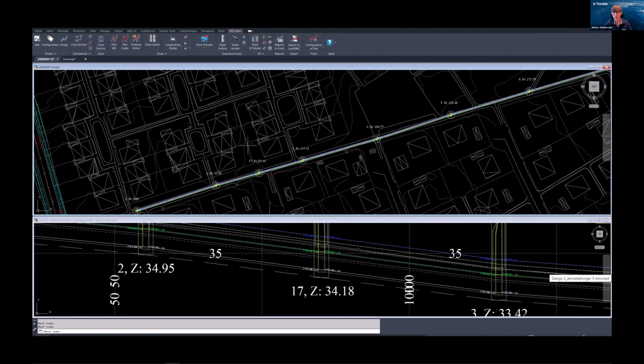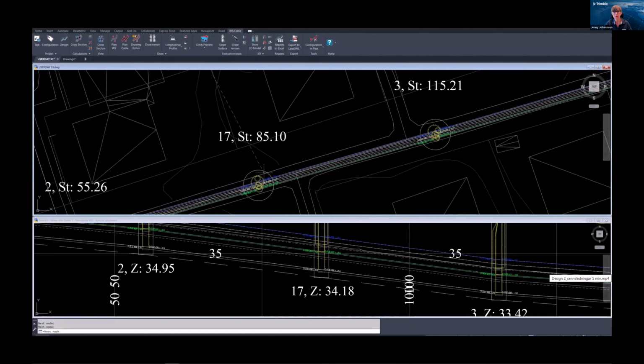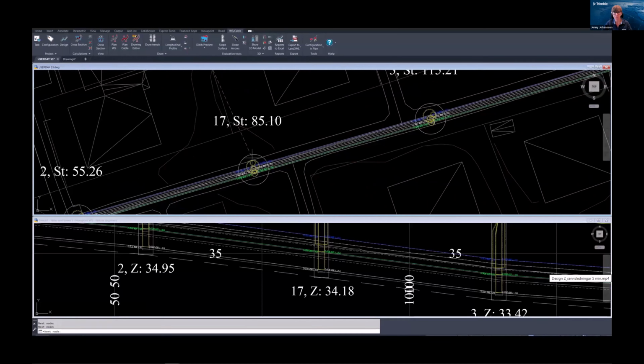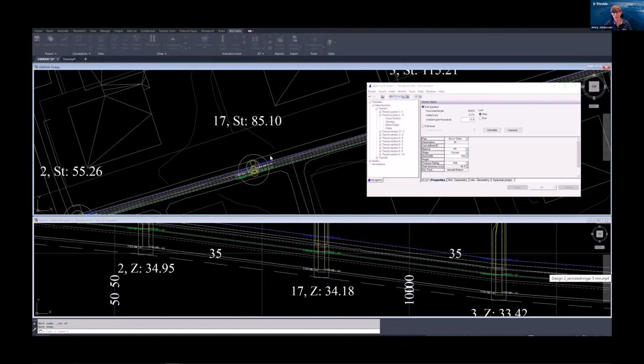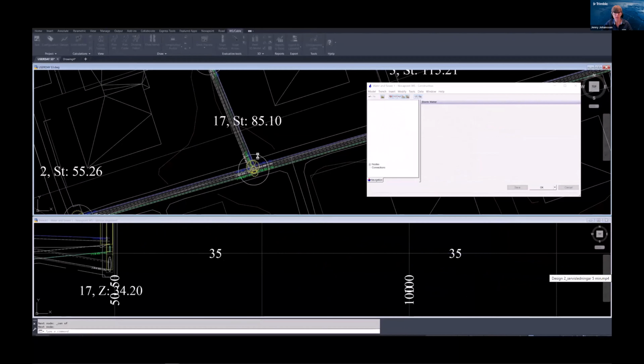When I want to join this existing node, I need to snap to center node. So I use the snap tool by finding center node, and I snap the trench to that one. This is because I want to use the connections that are already there. If not snapping, I will end up with 6 connections instead of 3.